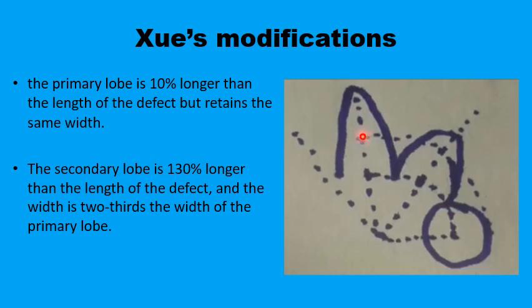And the same applies to the secondary flap, whose width can be a little bit reduced, to about 60 or 70% of the width of the first flap, but it would be stretched in length by more than 30% or so. This increase in length between the two lobes of the flap would cancel out any shortening effects.